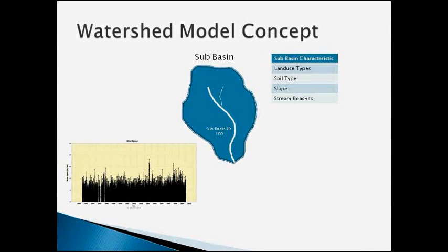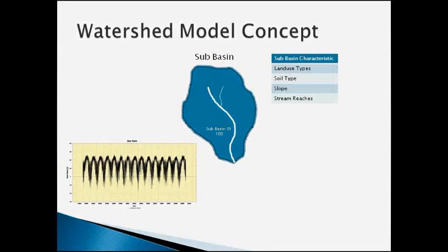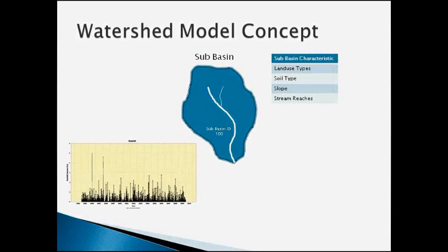Watershed models are typically forced by meteorological conditions, things like wind speed, solar radiation, dew point, air temperature, and the big driver of all is rainfall or precipitation data. These models can handle precipitation data typically from hourly to daily rainfall to predict contributions from the landscape.